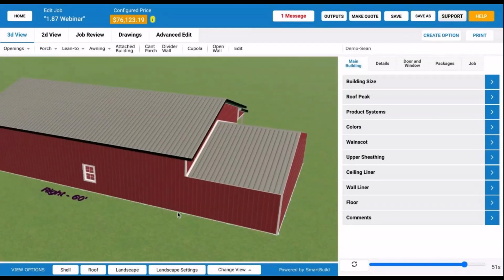Well, we did that just because if we combine roofs, people didn't want to start over their sheathing either, right? Not the exterior. Yep. You didn't want to have a new break point in your sheathing, and that would have been an issue. So there's a lot of things that run into each other. You can ask for one thing, but the reason why we did it the other way is because everybody didn't want to restart their sheathing. Same thing if you had one full building coming across here and it did combine the roof. Well, what are you going to do with the ceiling? And since the ceilings are combined with the roofs and the trusses, that's how all of that worked.